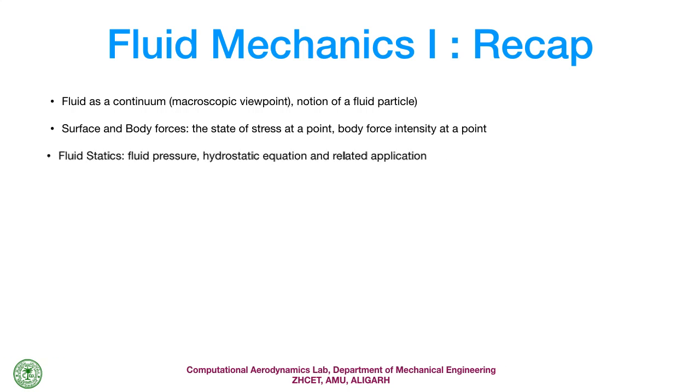The next point to consider, which we have already studied, is fluid statics, where you might have studied the notion of pressure. It is always compressive in nature, the hydrostatic equation and its related applications. The hydrostatic equation is minus grad P equals rho times (g minus A), that is, gravity minus the acceleration.